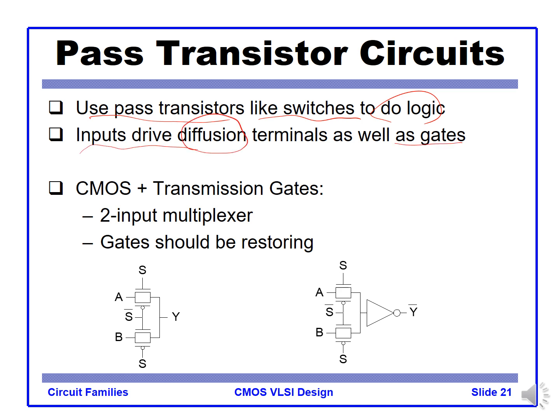gate, right? So let's find an example like a transmission gate like this. We have a pass transistor here, 1 and 2, transmission gate, here, PMOS and NMOS in parallel. We have a selection signal for NMOS and PMOS shown here. It just implements the multiplexer, right?